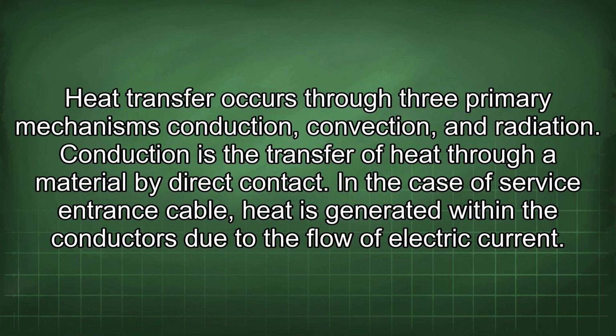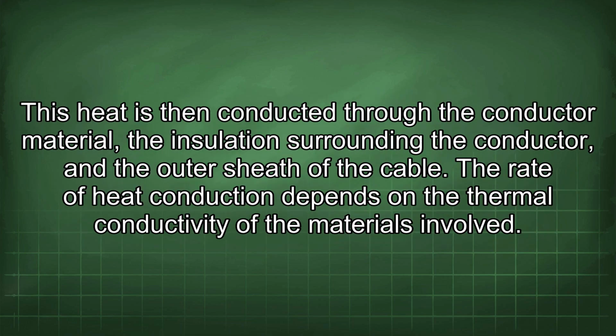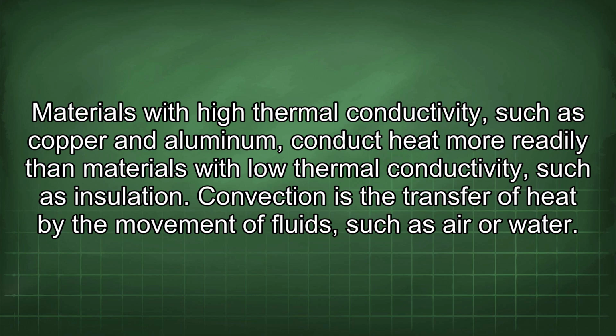Conduction is the transfer of heat through a material by direct contact. In the case of service entrance cable, heat is generated within the conductors due to the flow of electric current. This heat is then conducted through the conductor material, the insulation surrounding the conductor, and the outer sheath of the cable. The rate of heat conduction depends on the thermal conductivity of the materials involved. Materials with high thermal conductivity, such as copper and aluminum, conduct heat more readily than materials with low thermal conductivity,